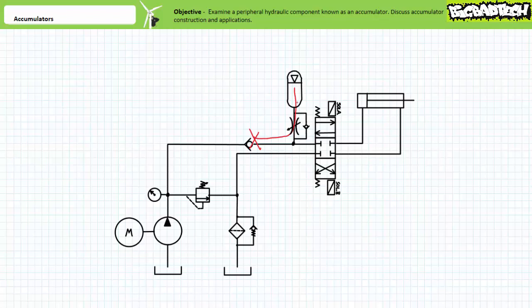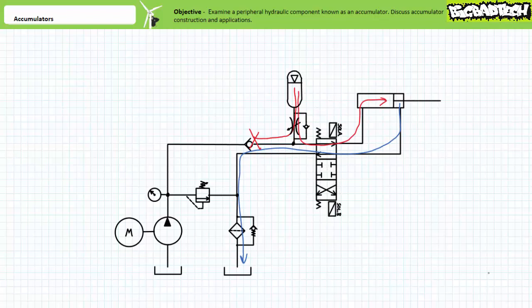Desired pressure, flow rate, actuator size, and cycle count must be taken into consideration when sizing an accumulator for this application. An example necessitating a backup source of hydraulic power would be the hydraulically pitched blades of some modern horizontal axis wind turbines. Pitch control systems in wind turbines continually monitor and adjust blade angle to ensure maximum power delivery, at the same time preventing dangerous overspeed conditions. In the event of pump failure, the stored energy in the accumulator can be used to rotate the blade back to the safe position and aerodynamically brake the rotor.